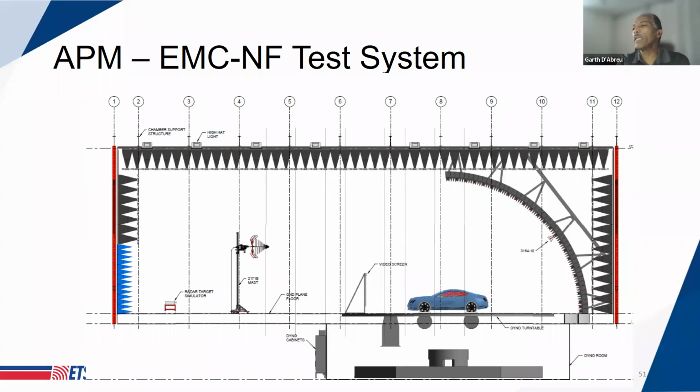This is an example of an implementation of, again, an upper hemispherical type measurement, where because of the short measurement distance, you're using near field scanning techniques and then using math to predict or calculate the far field pattern of the particular propagating antenna.